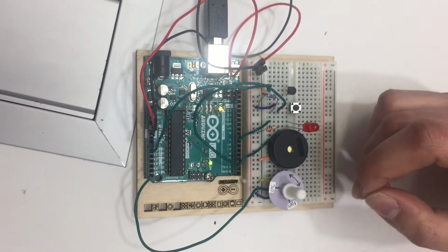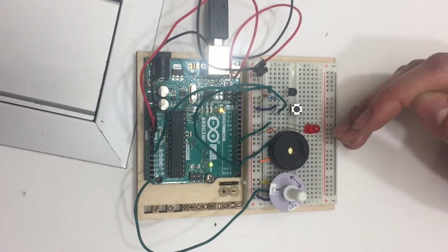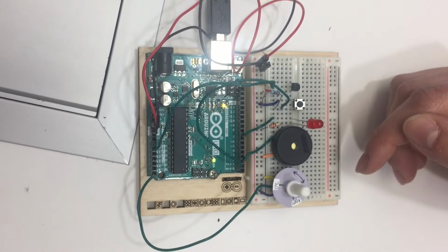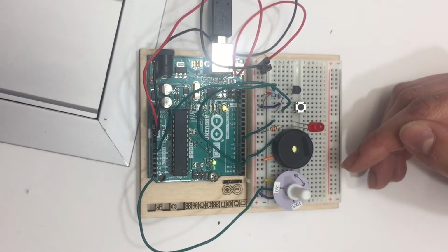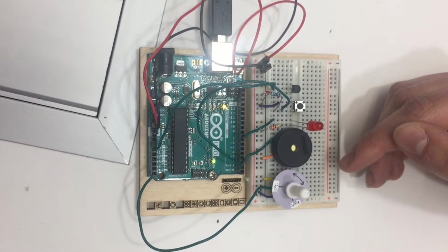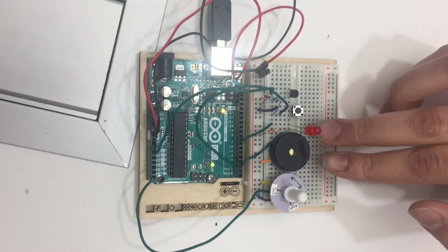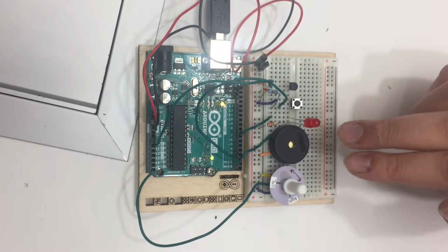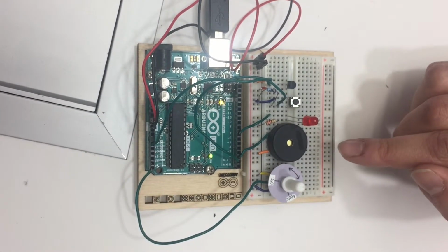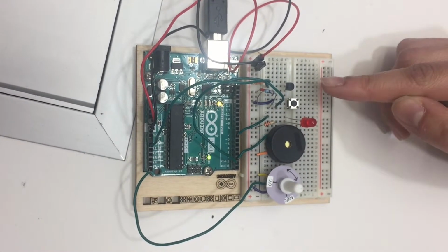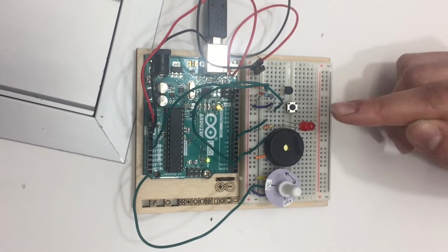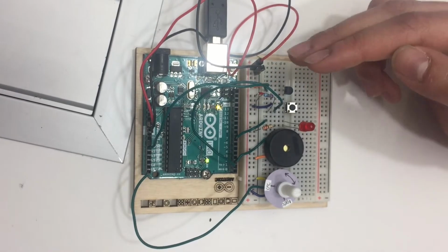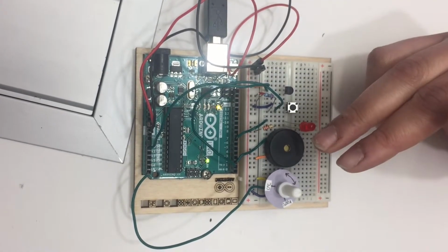Then we have the LED, which only lights up when the threshold temperature is reached, and it's a digital output that uses the pull-down resistor. We also have the piezo, which turns on when the temperature threshold is reached, and it's also a digital output. It's important to note that the LED and the piezo operate together, so they both turn on together and turn off together. The button is the digital input, and it uses a pull-down resistor to give a value between 0 volts and 5 volts, and it exits the loop and shuts down the light and the alarm as if it's a real alarm clock. We also have the reset button, which we use to re-enable the device after it's been shut down by the button.